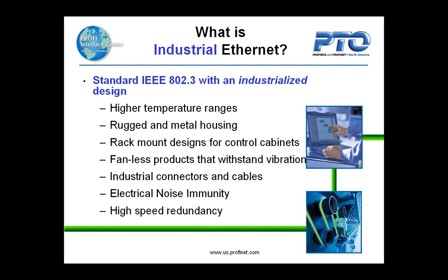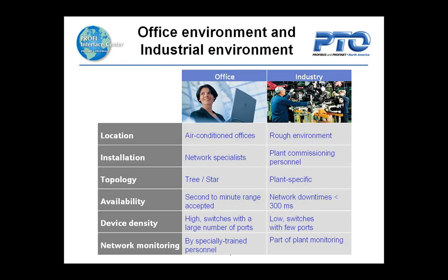So we might have to look at higher temperature ranges on the device, more rugged housing, maybe a more rack mount design, fanless products so we can withstand vibration, even industrial connectors and cables, and of course more noise immunity, and maybe even redundancy from a functional perspective. Because again, the office environment and the industrial environment are a lot different.